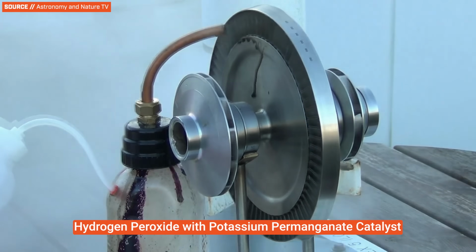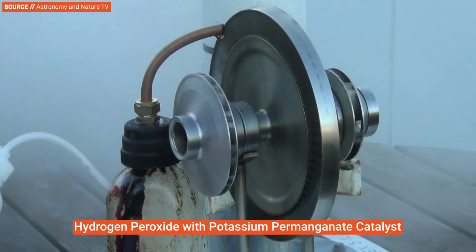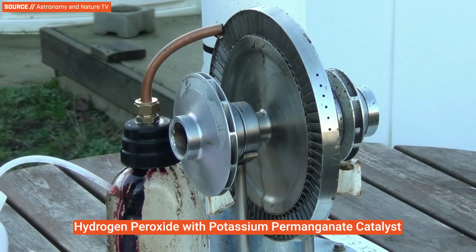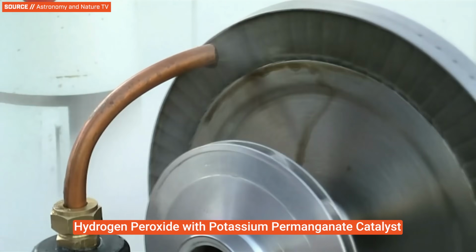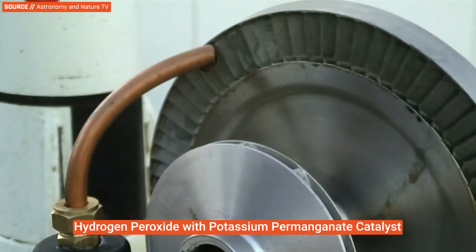Then the secret to monoprop's success is converting some chemical energy in the fuel into pressure and heat through some kind of energetic reaction. That's right, you can actually have an energetic reaction with just your fuel running over a catalyst. So if you use a fuel that's highly reactive and a strong reducing agent, such as hydrogen peroxide or hydrazine, and you run it against a catalyst bed like potassium permanganate or iridium-infused alumina, you can harness that chemical reaction to create pressure and heat.